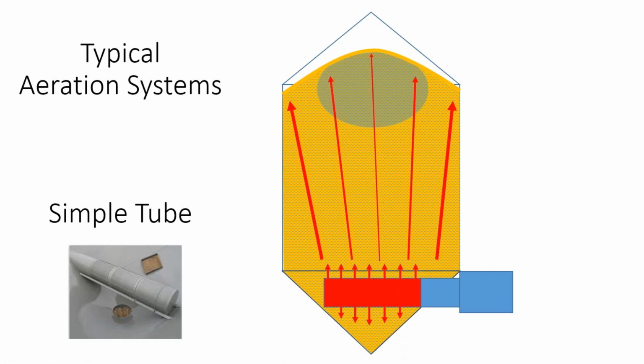And ultimately, when looking at air delivery systems, you want to find a system that provides an easy path for the air to get to all the grain and to get out of the bin by traveling through the least amount of path. And you can see here that a quarter of the air is traveling a very long path.